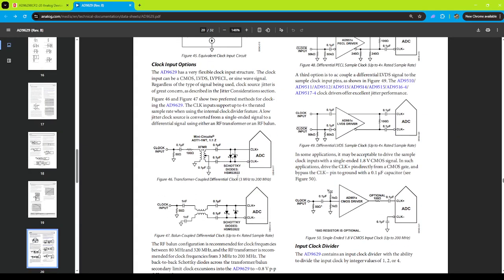This is very important. You need ultra low jitter because if you have high jitter, you're just going to ruin everything. Like, actually, the clock is extraordinarily important. You can't just feed any clock. You've got to condition your clock, and it has to have ultra low jitter. And I really mean that. If it doesn't have ultra low jitter, and you wonder why your SNR is bad, that is why. So I'm going to be clocking at 20 megasamples per second. Probably I'll use a 20 megasample per second part. So okay, boom, done. We're going to go with this.